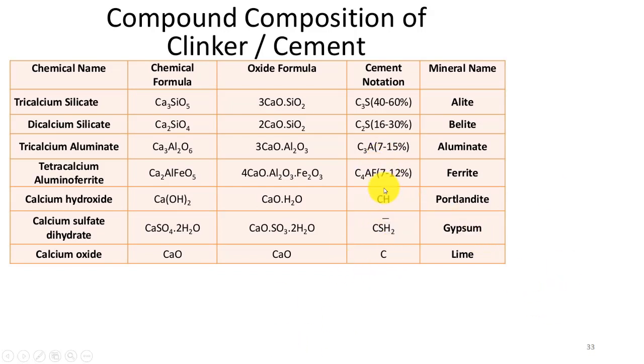This calcium hydroxide can be leached out by different cycles of water penetration into the concrete, and it can increase the porosity of a concrete when it's subjected to different freezing and thawing cycles, and it can degrade your concrete by leaching it out. So the byproduct Portlandite is allowed to have very low concentration in order to make your concrete very durable.